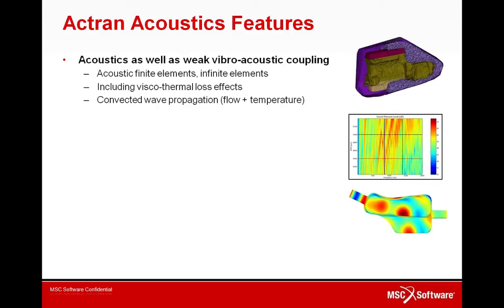So the Actran acoustic module is based on acoustic finite elements and acoustic infinite elements. If you look at the figure on the right-hand side, you can see that infinite elements are always combined with acoustic finite elements. Acoustic finite elements will be used to model the propagation in the near field of the source, and then acoustic infinite elements will be used to model the radiation in the far field.